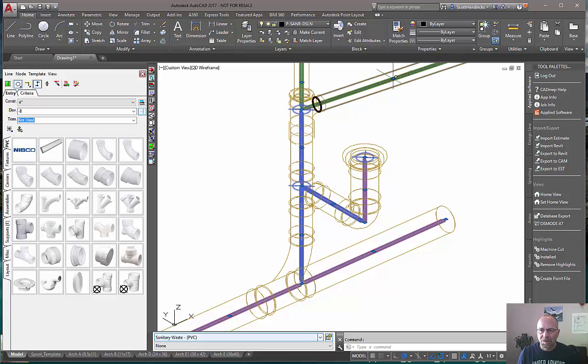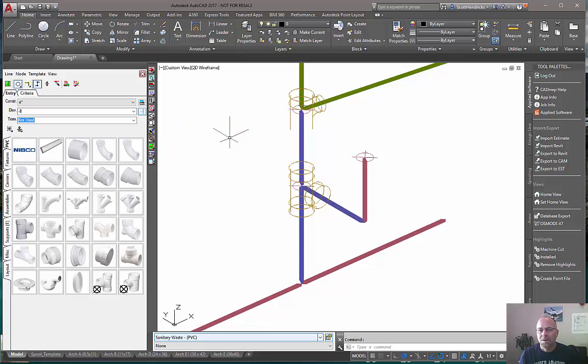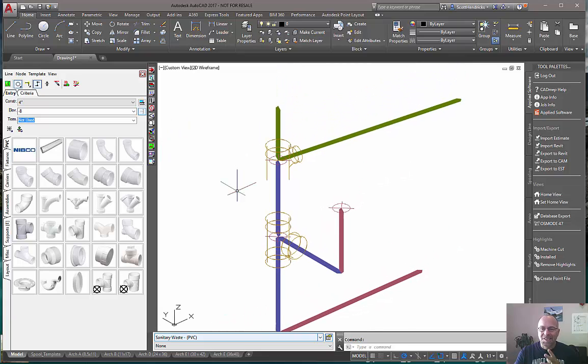So what we need to do is push this line down just far enough to where it seats into this Santee. To do that, I'm going to select my design line, select the Santee that I want to move, and the Santee that I'm going to move it into, and isolate those by selecting my isolate button. Now I'm going to make the change using AutoCAD's multiple grip edit.